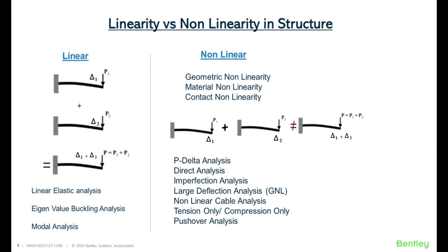Now, in our case, in this model, we have used the bracings as tension only. As I mentioned, the moment you use the tension only or compression only specification, you are considering the structure to behave as nonlinear. Now, as it's nonlinear, we can't use the load combination.